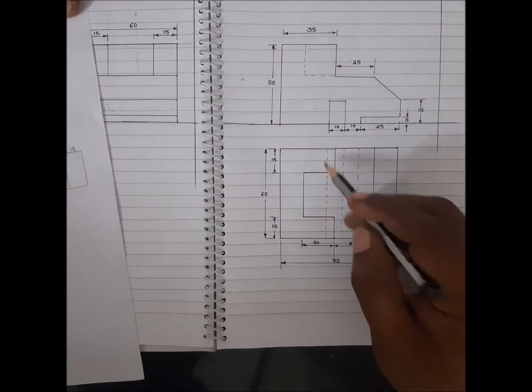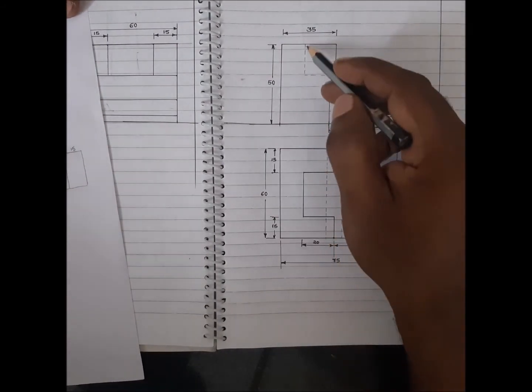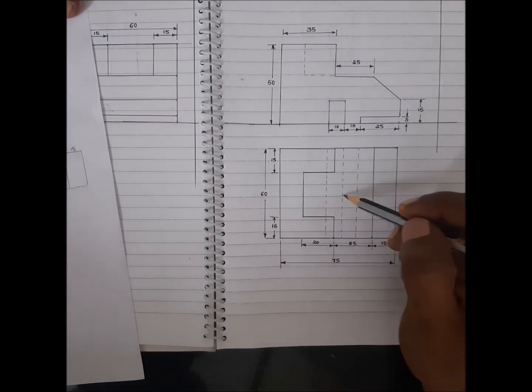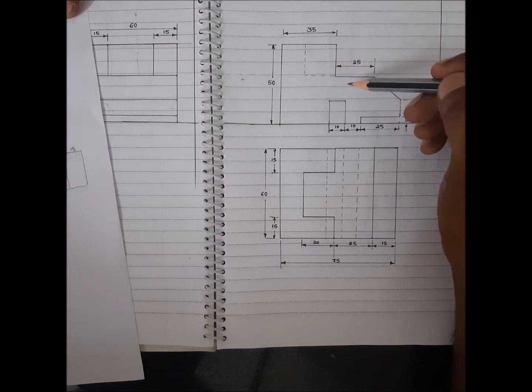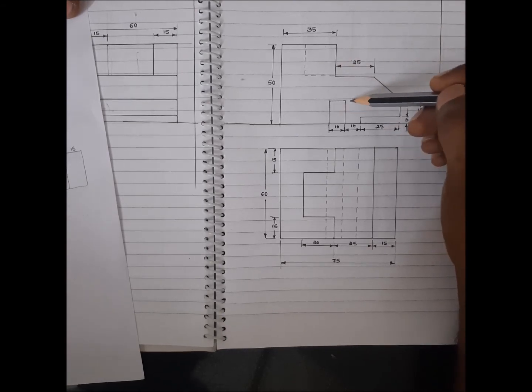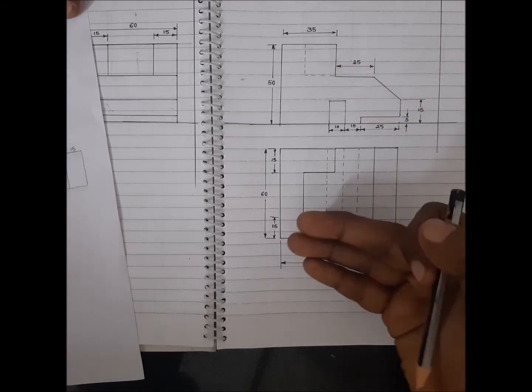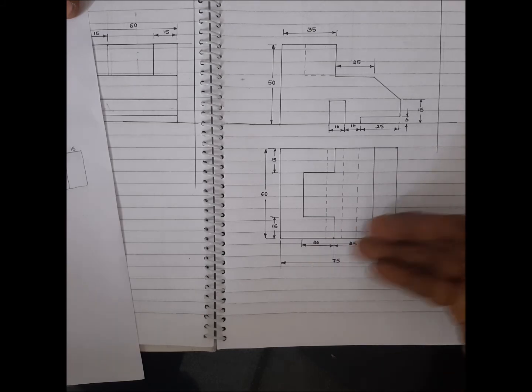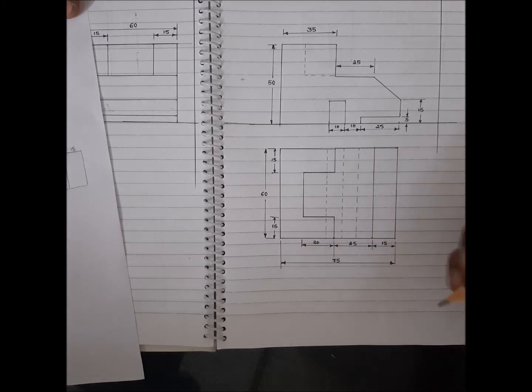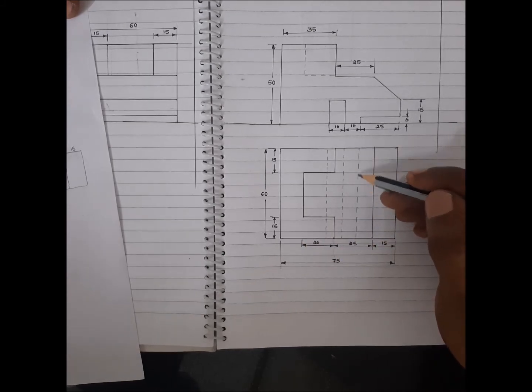Right. So when you look at this figure, you can make it out. The front view looks like this, but there is a pocket over there, and there is an edge going like that. And how do you find out that edge? When you look at the top view, this is why you have an edge there. That's how you make it out. And if you see these edges, in the top view there are three. There are some edges lying beneath the solid, so that is what this indicates.